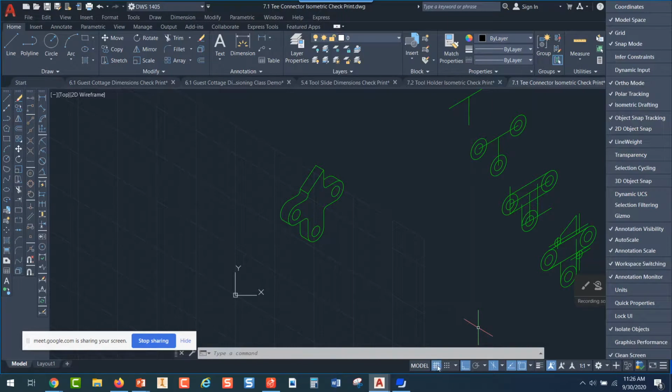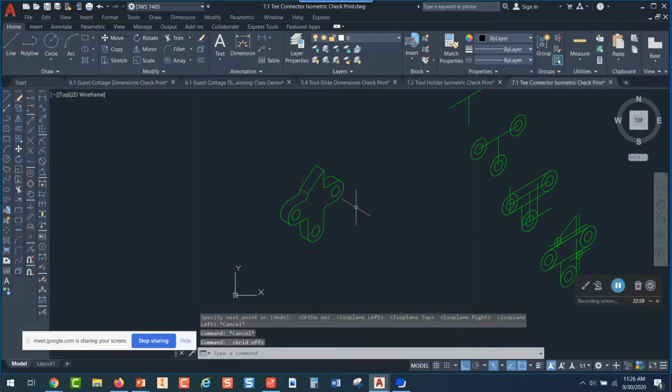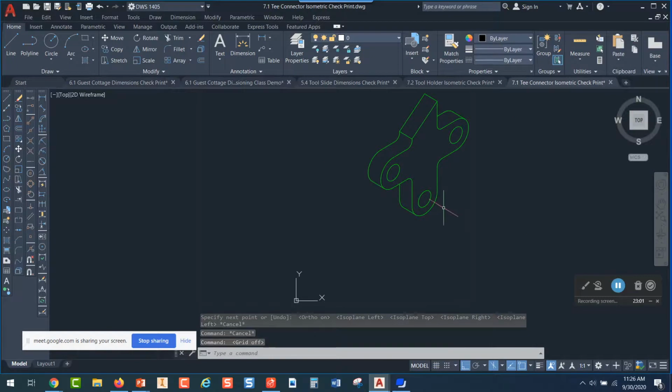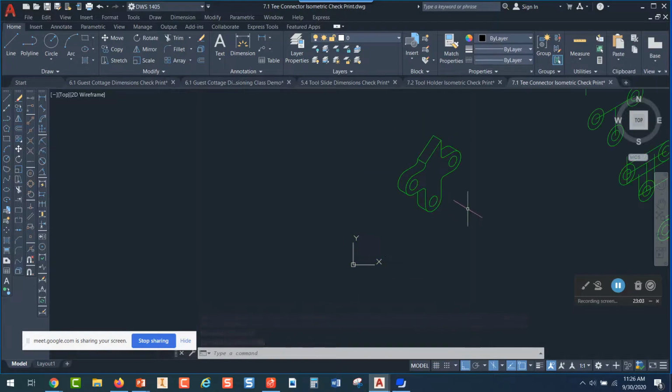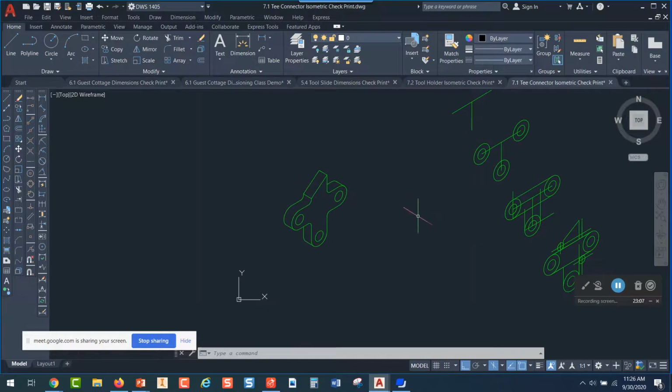Usually I don't have my grid on, and I sure don't have snap on. So, you know, we have those on, but I'm not a big fan of those guys. You know, so I want to make sure I turn my grid off. So we're going to be starting this drawing kind of near our UCS. I think it'll give you some coordinates to get started, but you can move it around wherever you need to.